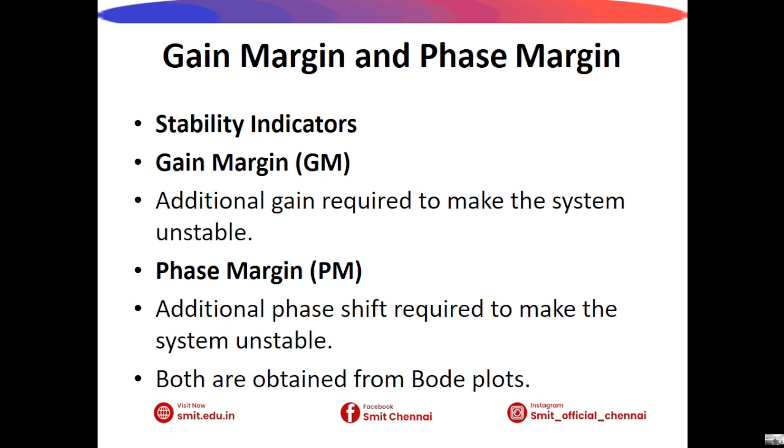Gain margin and phase margin. Gain margin and phase margin are important measures of stability obtained from both plots. Gain margin tells us how much gain can increase before instability occurs. Phase margin indicates how close the system is to oscillation. Larger margins generally imply greater stability.